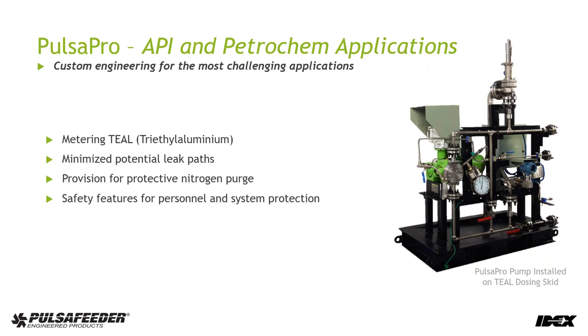Just a little bit about TEAL. It's considered a pyrophoric chemical that is flammable when it comes in contact with oxygen or just air. So it needs to be completely isolated. And you can just do some YouTube Googling and look up TEAL, and you'll see some pretty interesting videos about that. It cannot be extinguished with water. In fact, water just makes it more flammable. So it's a fascinating chemical used in the manufacture of plastics.